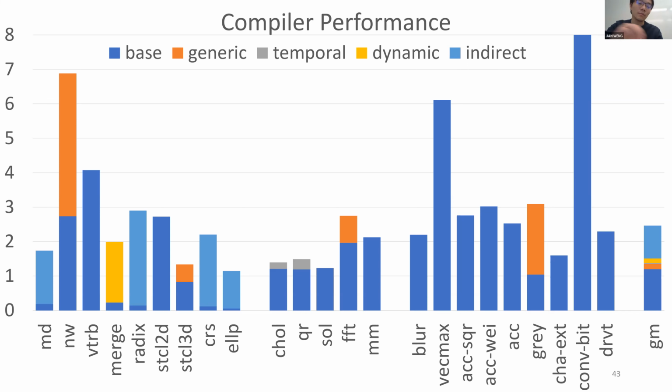If we are doing an area normalized performance, that should be 100 times higher. Oh, I see. And the performance you demoed is not normalized. Yeah, it's not normalized. It's just our compiler on that. If we do an area normalized performance, even for a single core, we just cut a single core of the EPYC CPU from the die photo, we still have 100 times area normalized speed up. Because we are specialized for the interdependent instruction pipeline. No matter how wide the issue window of an out of order core is, it cannot achieve that effect.